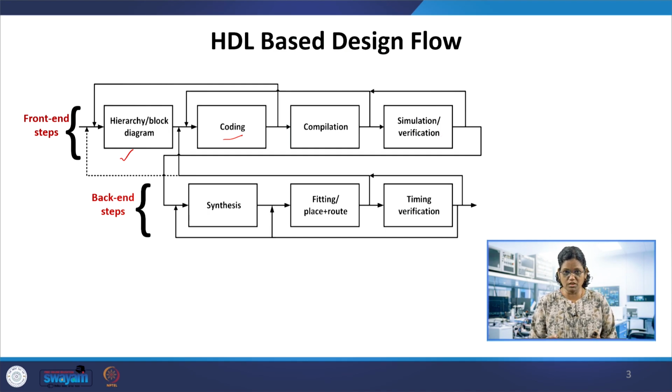So, the design flow and the tools used for HDL design have two distinguished paths, 1 and 2, and these two are cascaded one after the other. The first part is the front end, and the second part is the back end. The front end part is what we have done so far. We would like to give more detail about the test bench, what is simulation and what is synthesis, and more on synthesis will be discussed when we do the real time implementation of these Verilog modules in the FPGAs.